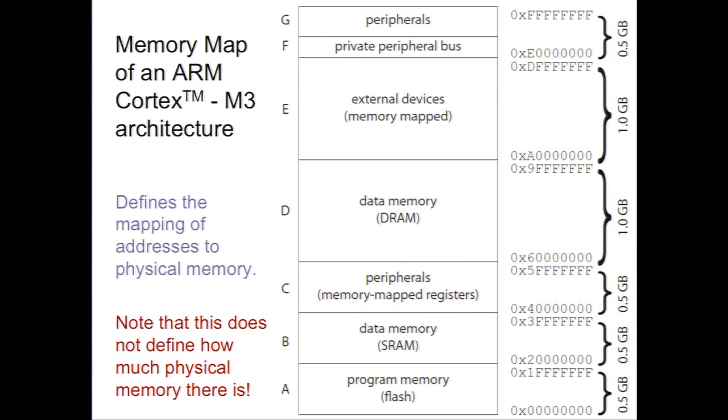So what does it mean to have a 32-bit address? Well, it means you can address 2 to the 32 locations, which is 4 billion memory locations. 2 to the 32 is about 4 billion. So you have a 4 gigabyte memory space. And the addresses are 32 bits, which we typically write in hex. So you'll get used to reading a lot of hex if you're not already used to it. But each symbol here represents 4 bits, so there's a total of 32 bits here.